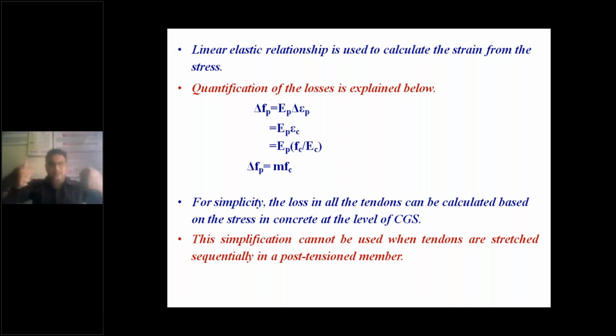So let's start applying some force on the composite material. Because stress is directly proportional to strain, whatever the stress carried by the materials, the strain will also be the same in the concrete and steel. Why? Because individually, members will have different strains. Understand? Steel and concrete will have different strains based on the application of the load.